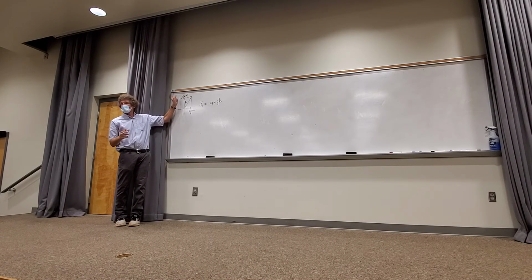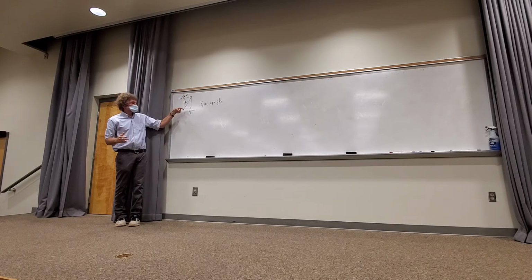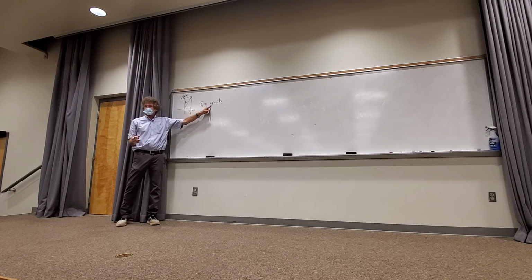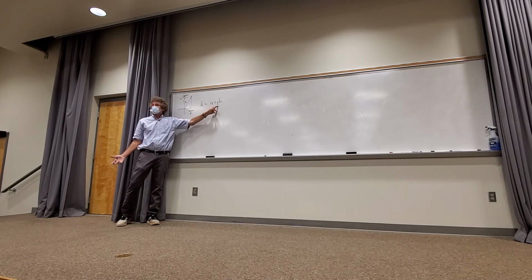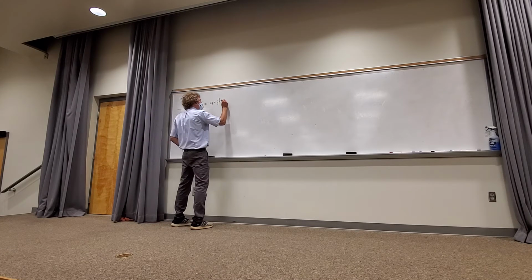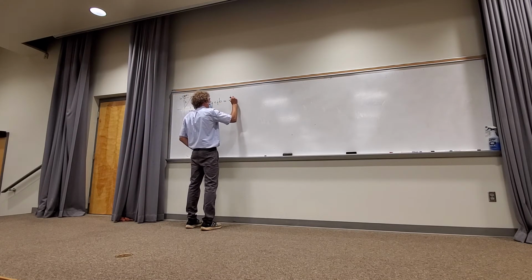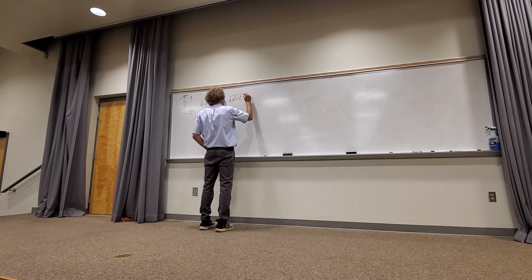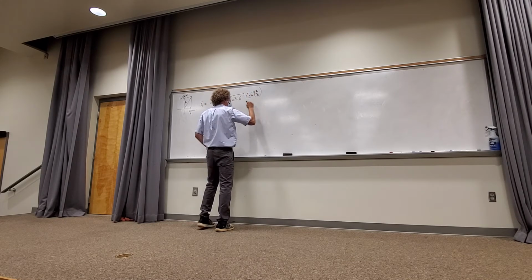The imaginary axis is vertical. The real axis is in this direction. a has no j in front of it. It is a real number, like 10 or 12. The jb, j times anything, if b was 10, that would be an imaginary value. Y'all with me on this, class? Now, that is equal to the square root of a squared plus b squared in magnitude, and it's at an angle equal to the inverse tan of b over a.